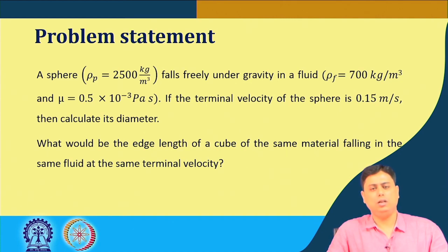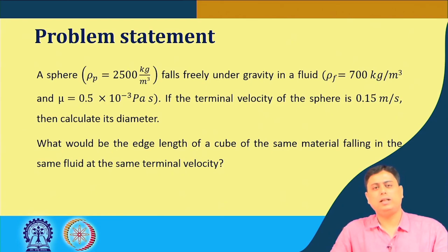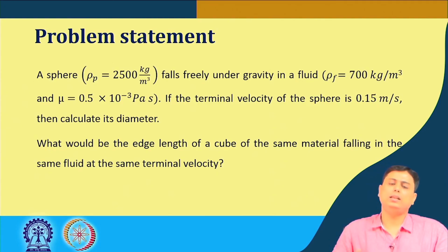Which means if we think of Stokes law again, the terminal velocity expression, we can see that there is a ut expression. But the point here, let me reiterate, is whether the assumption of Stokes law is valid, because you do not know in which region this terminal velocity is attained. Now, you remember that CD versus RE plot. There, at the first part or at low Reynolds number, we had the Stokes law region, then the intermediate region, then Newton's law region, and then the boundary layer separation region. So, this terminal velocity is in which region?